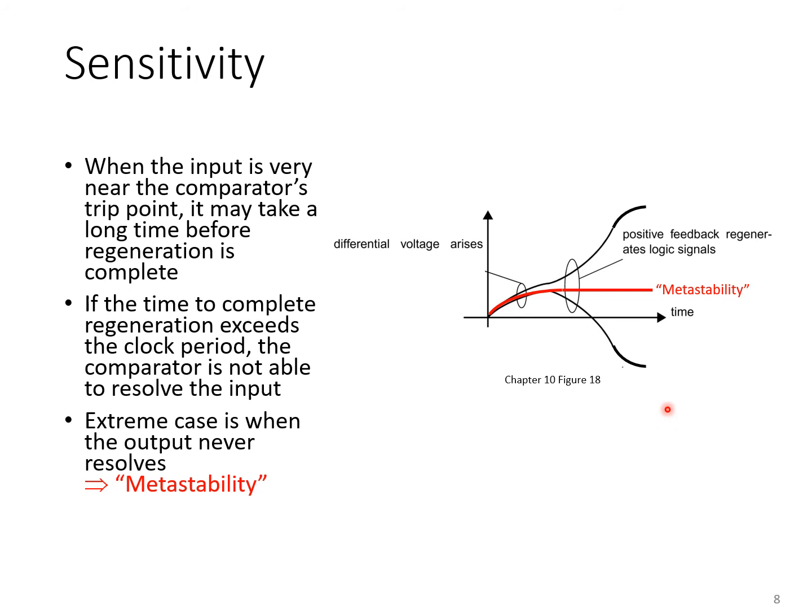But sensitivity should always be measured and reported with reference to a specific clock frequency. At that clock frequency, you only have a certain amount of time for the latch to regenerate. And if the latch hasn't regenerated by then, well, then we say that the latch was metastable there.